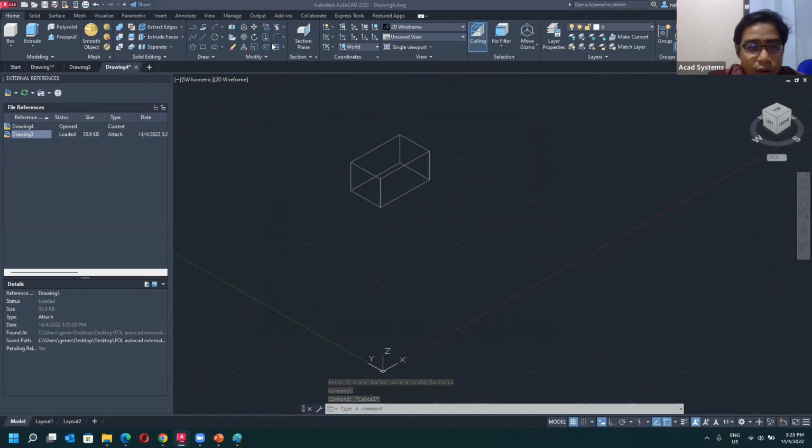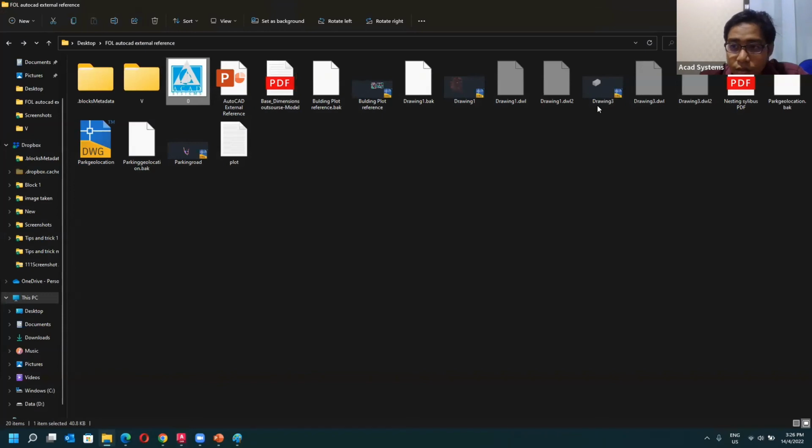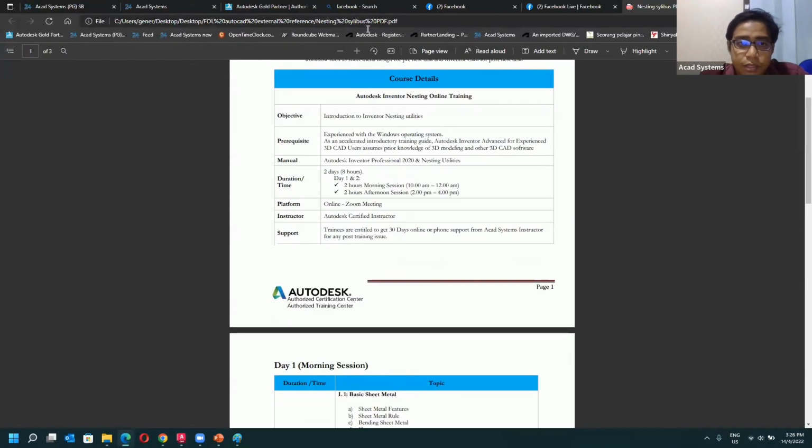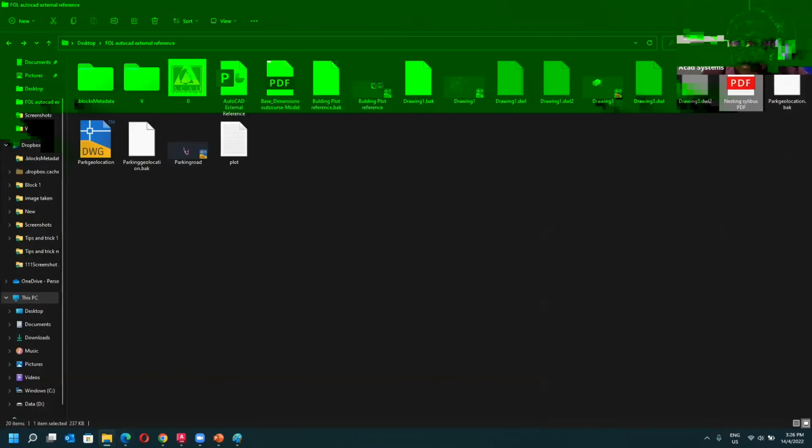Okay, so we have one question from the CCW. Will a PDF file inserted into AutoCAD become MText or an exploded object? The MText appears because you have text. Any text that you have in your PDF files, for example, this particular text over here, will be automatically converted into either single-line text or multi-line text. So that one has been converted.